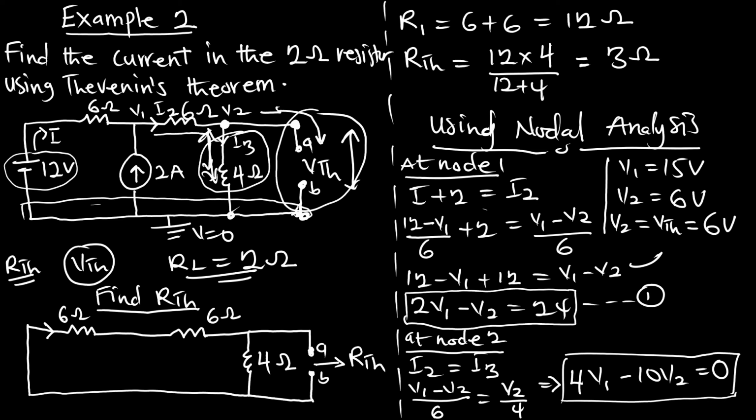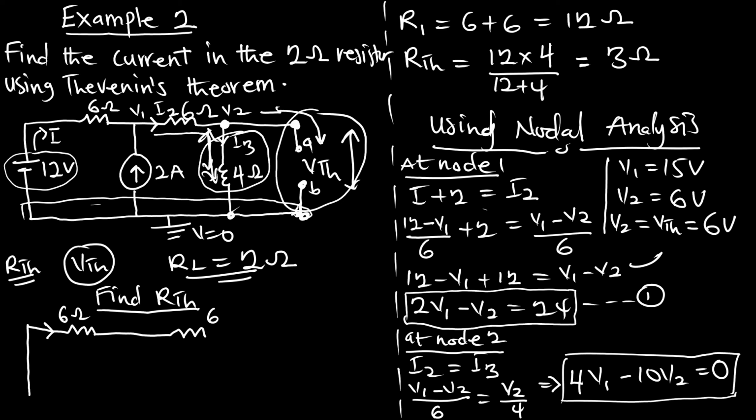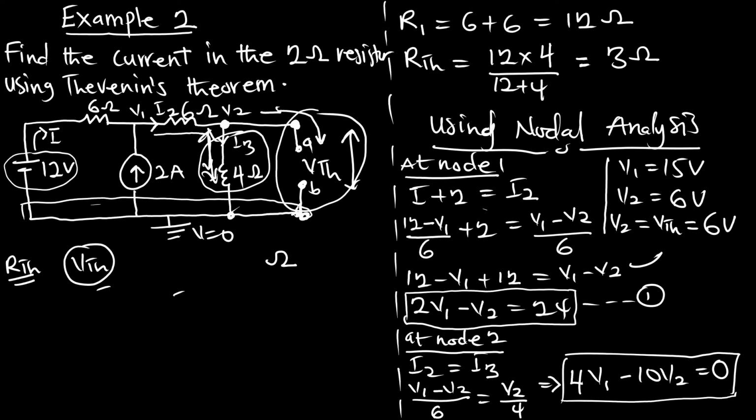So we can now draw the diagram for the VTH, the RTH, and the load resistor in series. Once you get to this point, you are through with your solution and you can move so easily. So let's draw the series arrangement and get the analysis.